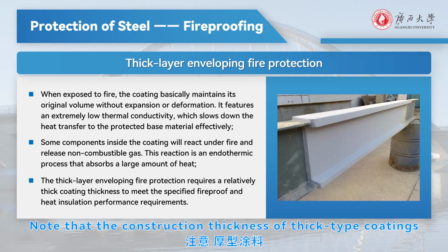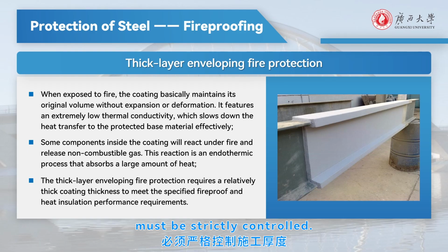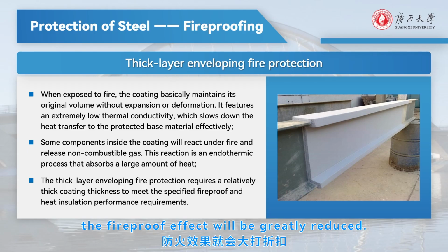Note that the construction thickness of thick-type coatings must be strictly controlled. If the thickness is insufficient, the fireproof effect will be greatly reduced.